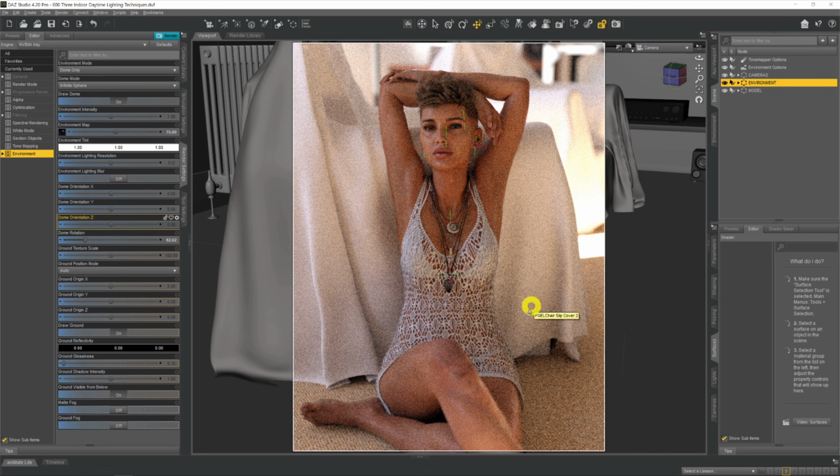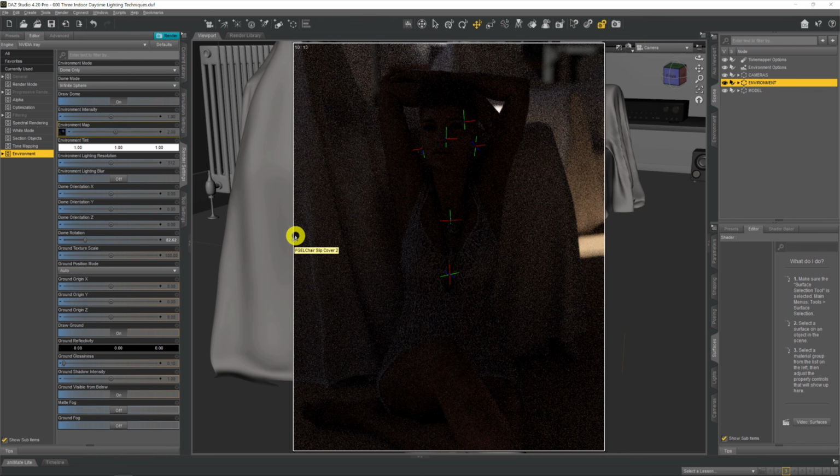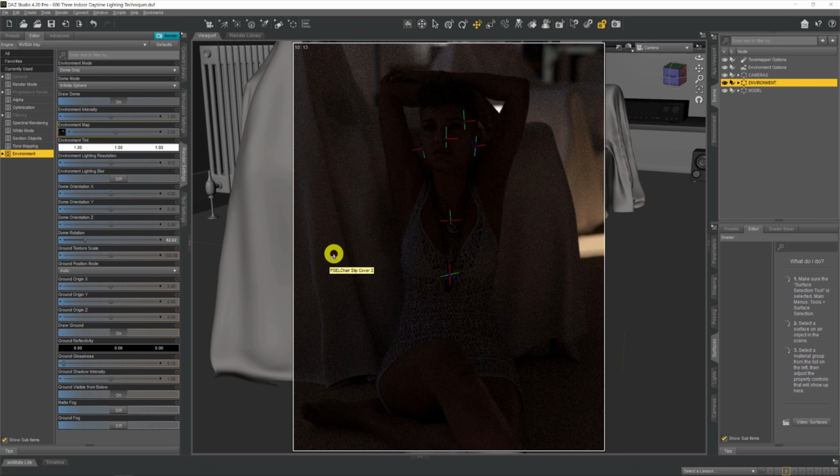be increased somewhat. And the reason being is because we're actually working with a low amount of light, and as we all know, iRay loves light, and if you don't have much light in there, it takes a while for it all to clean up and for you to get a clean render. So using this method will increase your render time somewhat. So just bear that in mind. If you haven't got the top of the range graphics card, things might be a bit slow dependent on your